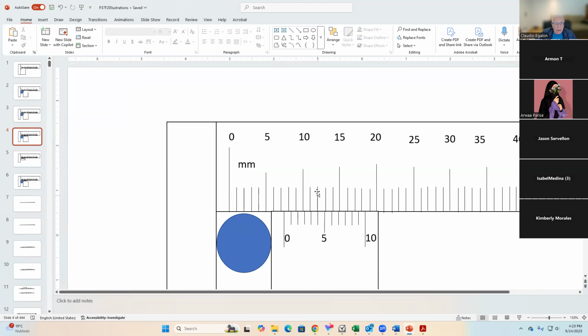Gotta see which one lines up with the one at the top, okay? Look what's happening. As I move forward here in this vernier scale, this line starts to get closer and closer to its corresponding upper line, okay? See, this one is closer, closer, closer.